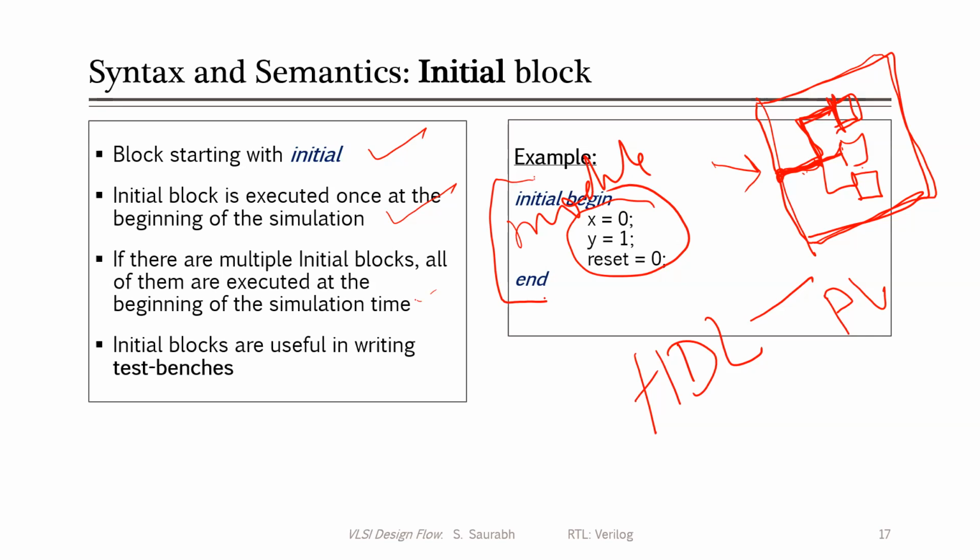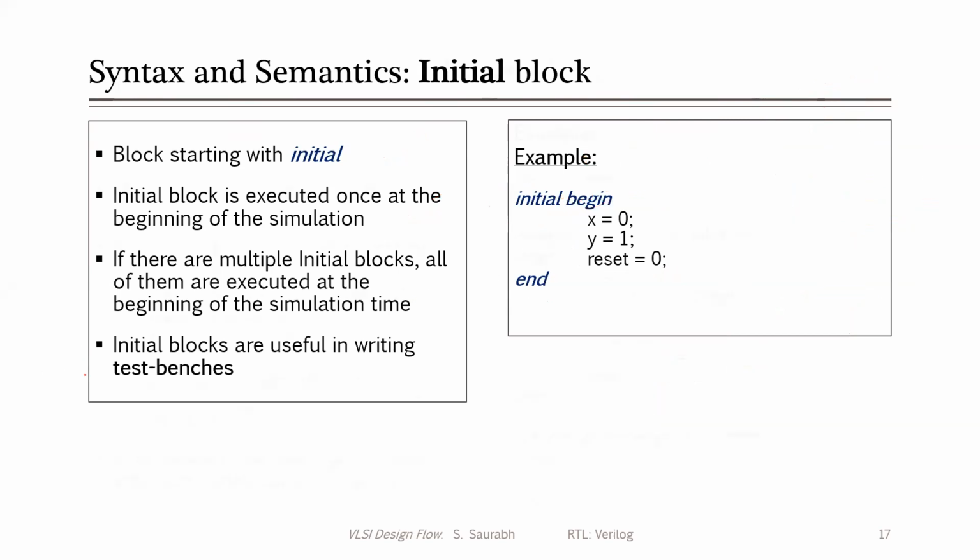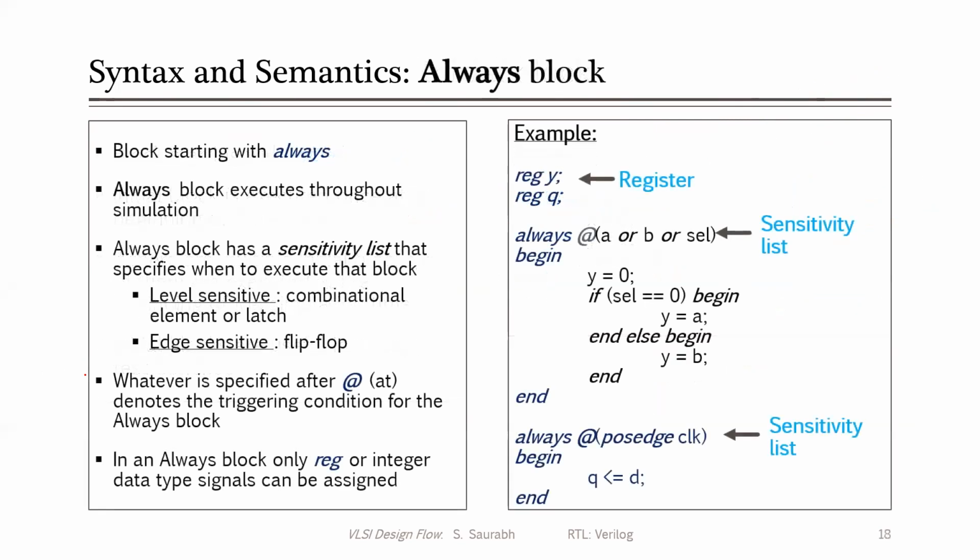Okay. And these initial blocks are very much useful in test benches. You initialize your design to a certain state or initialize your signals to a certain state. For those purposes, initial blocks are used. But these initial blocks are not synthesized. We'll look into that later.